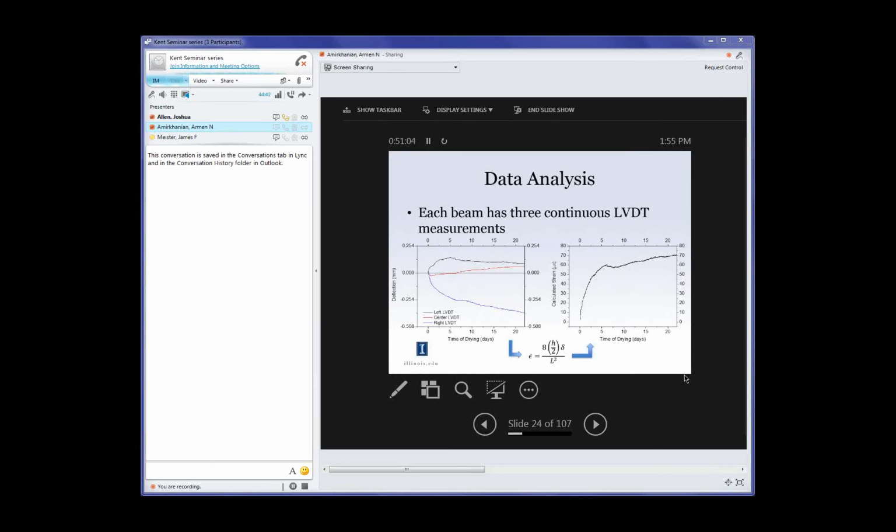That is definitely true. But why didn't you just instrument in the vertical direction? Purely because this equation becomes very difficult to calculate the strain because you have liftoff from your subgrade. So let's say we place it on a perfectly flat steel beam, very rigid. It starts lifting off that beam, so the contact area is constantly decreasing.